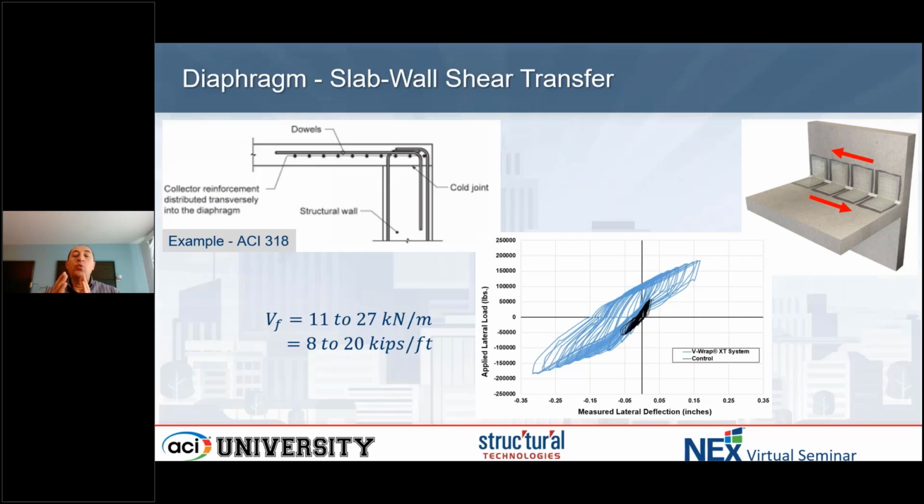And if you think about it, when you have these coupling beams, which is the small beam above a door or an opening that connects two big shear walls, you have a slab most of the time on the top side, right? Let's say if you have an elevator shaft, you may have a slab on one side. If it's an intermediate shear wall, you may have a slab on both sides. So you need to be able to confine the beam. You have to go through the slab, which means you may have to drill holes through the slab and use these FRP bundles to go through the slab and extend them down, and then put the FRP and provide that confinement that is required. And if you look at new design for coupling beams, we have a lot of steel in them. We really try to provide confinement and ductility.